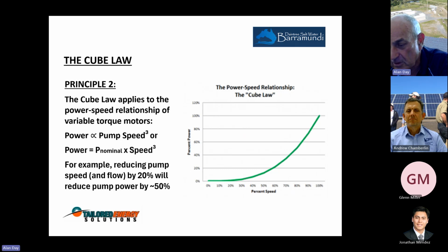We talked about using VFDs on the paddle wheels. Now you can use one VFD with two motors if the motors are the same size and the cables are reasonably much the same length. And if it's a small motor, you don't need to worry about some of the things too much, like shielded cable and sine wave filters and all those things that add a bit of cost. So we said they have 28 paddle wheels at the farm. If you just did one pond, you could set it up and experiment with it. And this means it's not a massive cost to start with.